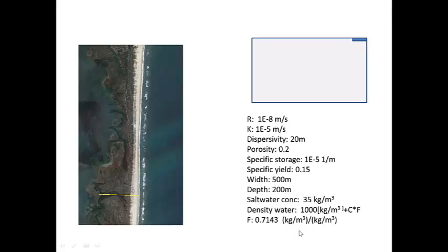So in order to do this, we'll use GMS, and we'll set up a MODFLOW model to simulate the flow, and MT3D to do the transport, and we'll use SEAWAT to do the transport. It is similar to MT3D, and we'll use it along with MT3D, but SEAWAT has the capability to have this density function in here.